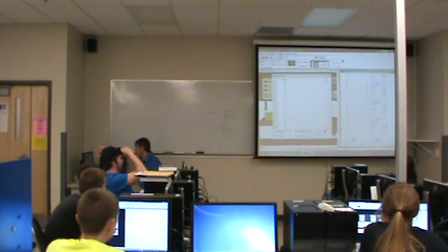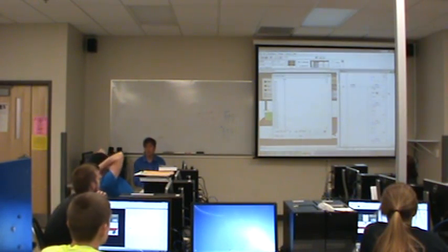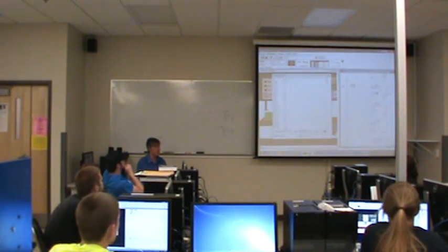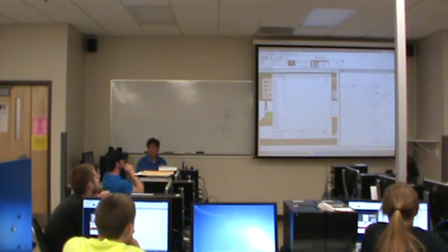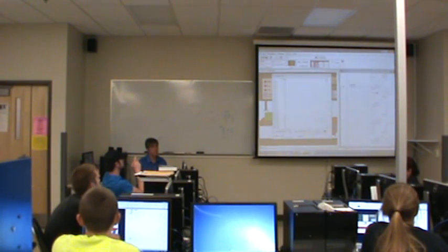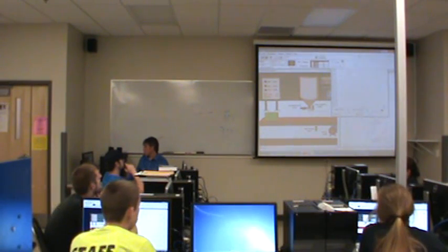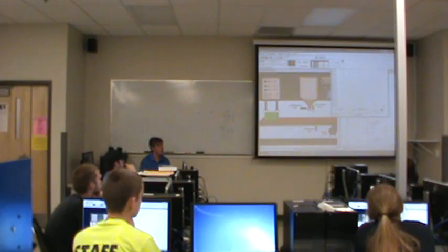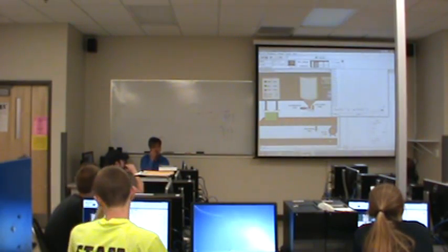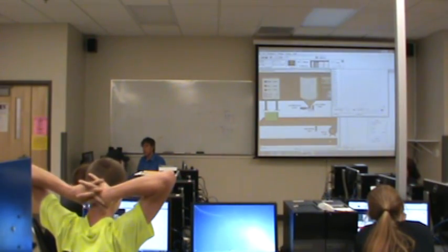Now I'm going to let you guys help me a little bit more. What should my mask look like? Should it be 15 or something else? I'll give you a hint. I'm looking at the outputs. What output bits am I interested in changing? The motor and valve. That's right. What are those bit numbers? 0 and 1. That's right. If both bit 0 and bit 1 are on, what's the decimal value of Y1? 3. That's right. Everybody follow that?